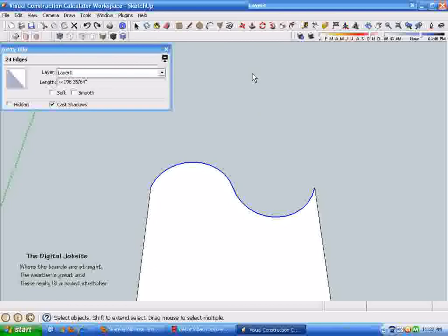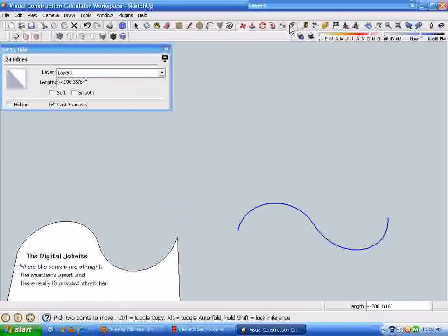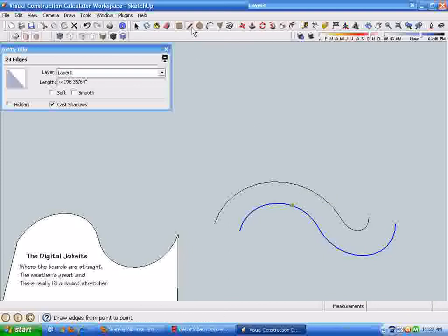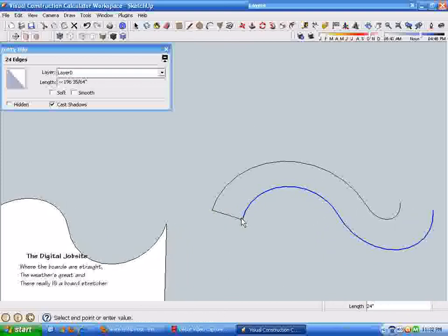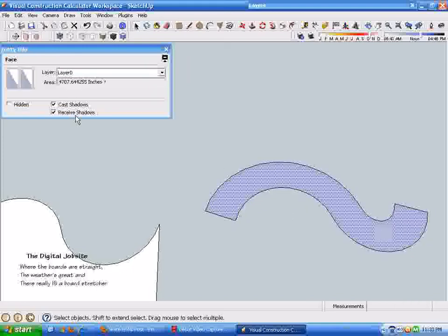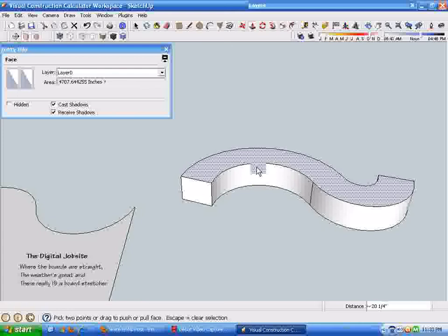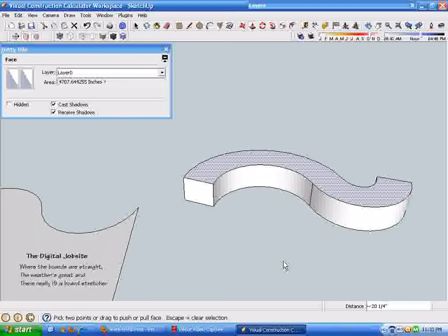Another thing we could do is by copying this geometry, oops, I want to get it to slide over here, red direction. I'm going to offset this curve, let's say 24 inches. So we need a little pathway that had that shape. So I just copied the curve, used the offset tool to create my little sidewalk, and by adding a couple lines in there, all of a sudden I've got the area of a sidewalk, and we can do the same volume thing here by stretching this up any dimension we need to.